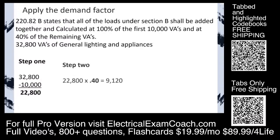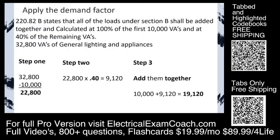Then we take that remainder at 40%. Then we can't forget to add back the 10,000. And we end up with 19,120. It's that simple. Then all we have to do from there is calculate the heating and cooling. We're going to choose the larger of the 2, and then we total those 2 numbers together, and that's our whole home load calc.